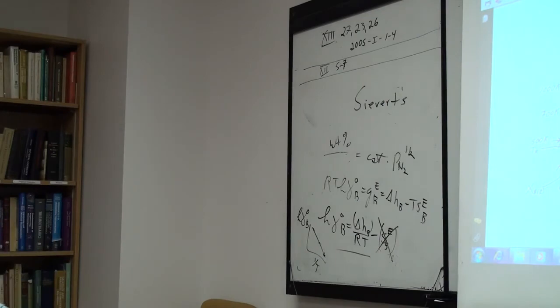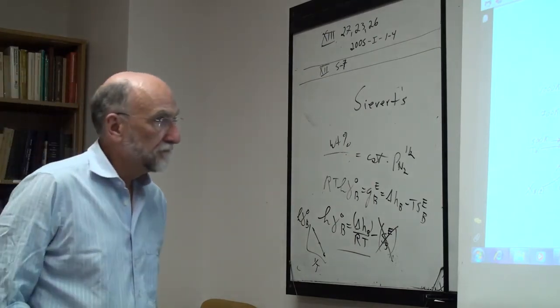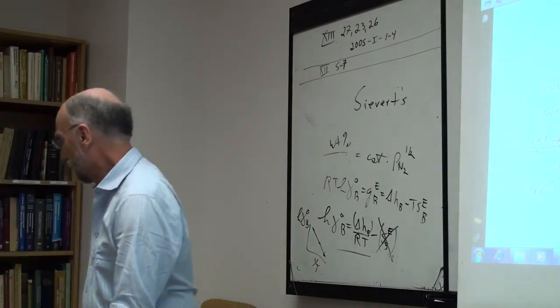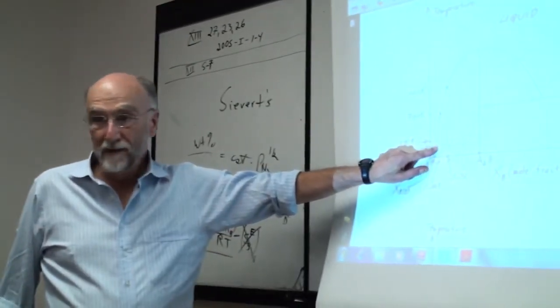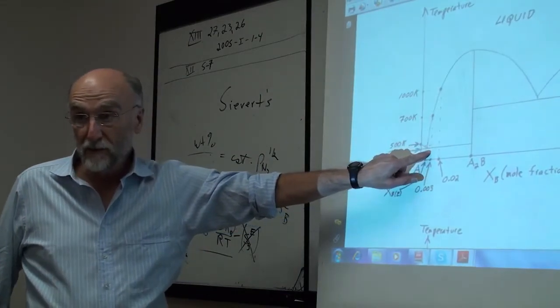In the first eutectic point, the second liquidus gives the activity of A. Yeah, but you don't need that. I'm asking to make sure for myself. And for the second one, the first liquidus gives the activity of A, and the second one gives the activity of B. Yes, this liquidus gives you the activity of A, and this liquidus gives you the activity of B.